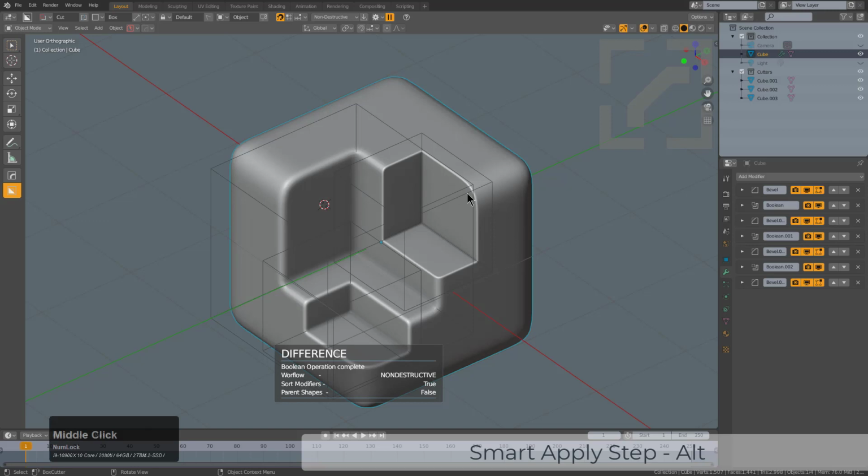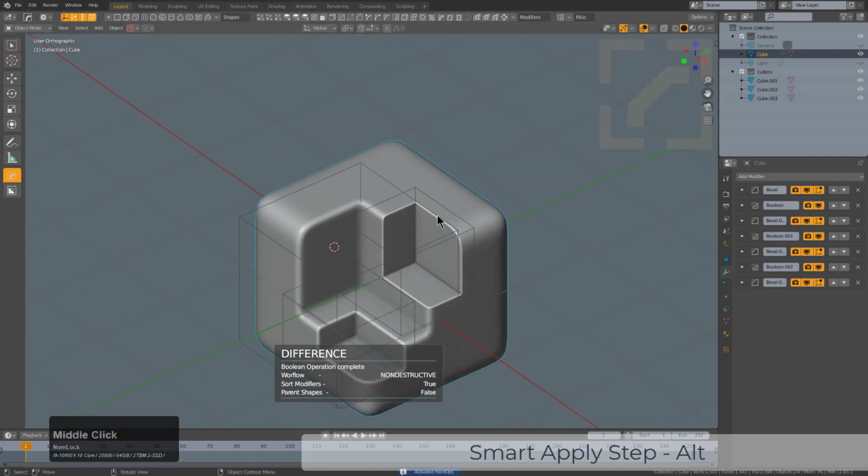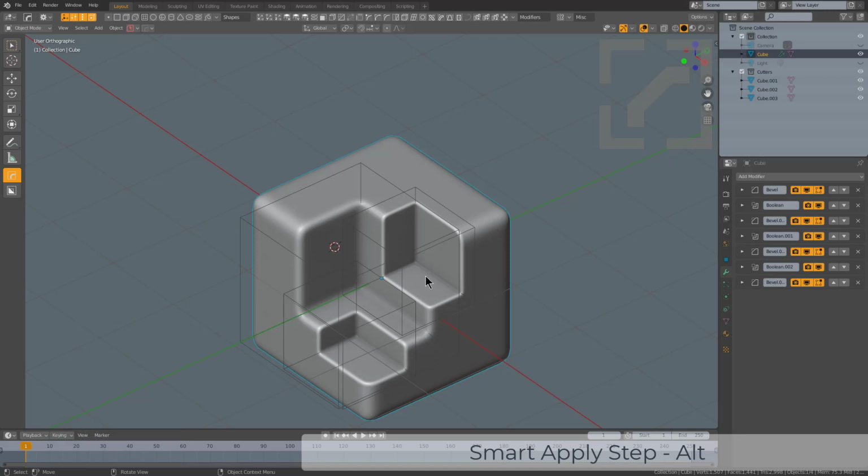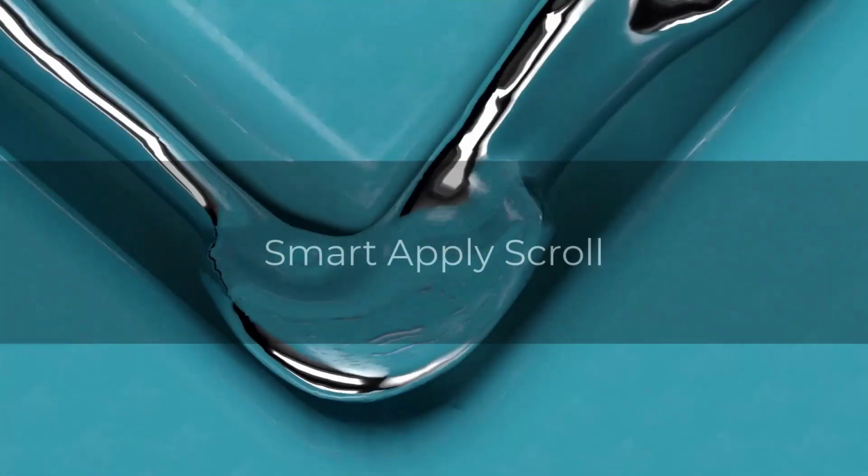And to look at this kind of experience in action, we can press Alt W, switch over to Hops tool, where if you hold Control, you can bring up the Hops dots, and we can just drag these to see each of our bevel levels in action. So while it appears to be very non-destructive, there are some limits to exactly how much you can bend and break all of your previous levels before you begin breaking things that are connected to it.